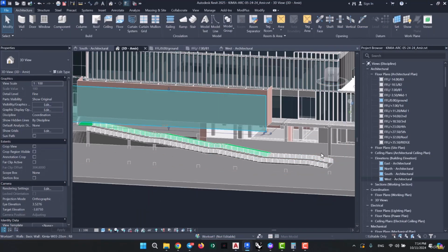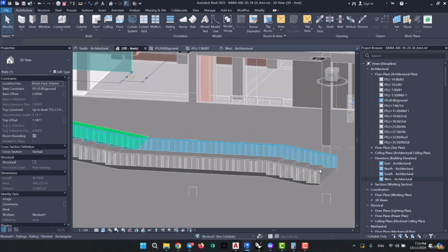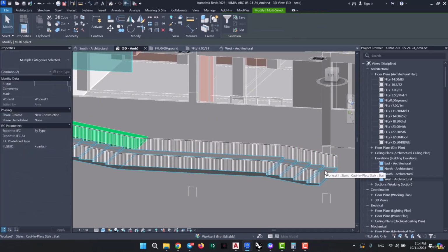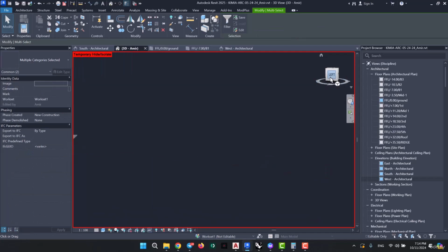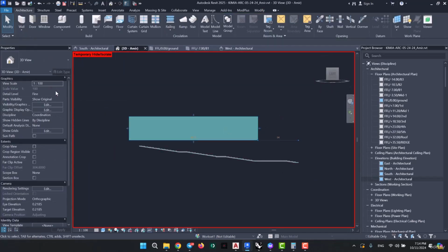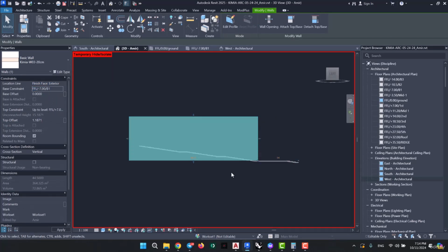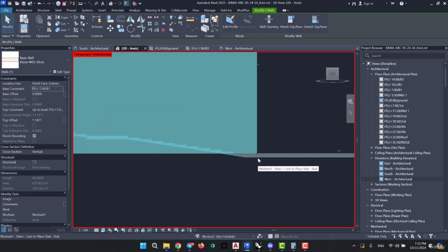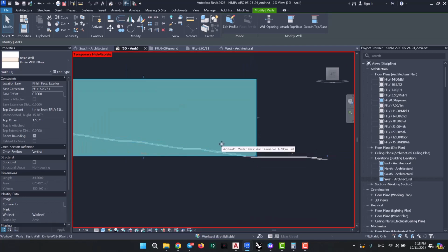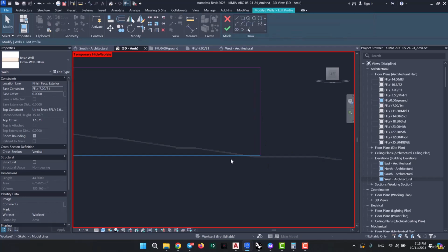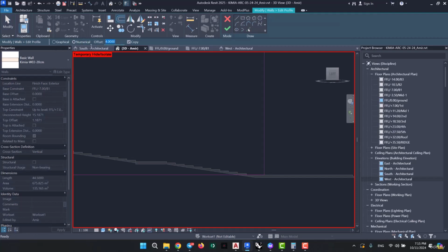Therefore, I'm going to go over here and select this wall along with the stairs. Then isolate both elements. Then we go to the 3D view. And first we will adjust the wall's offsets. We said that its base should be -7 offset, which is the first FFL. So it begins from here. And now we're going to adjust it with the stair slope. So I'm going to go over here. And first I'm going to put a 65 centimeter offset to this wall. And this is what it's going to look like in the first step. Alright?